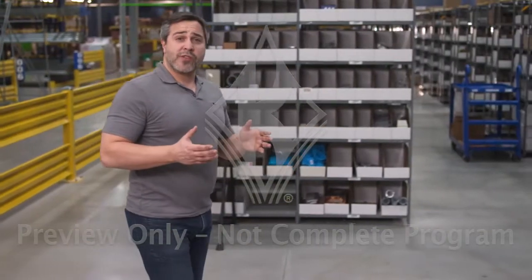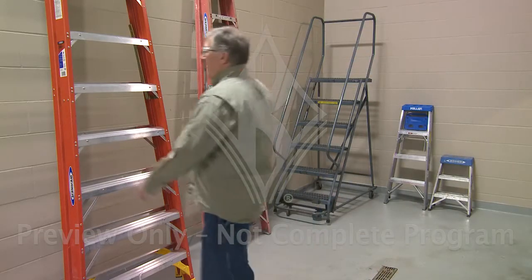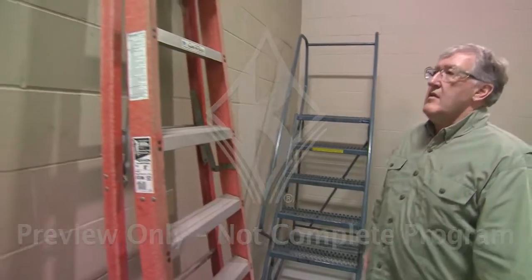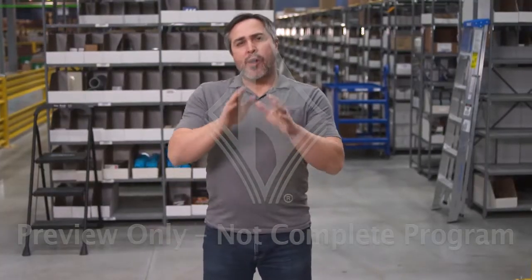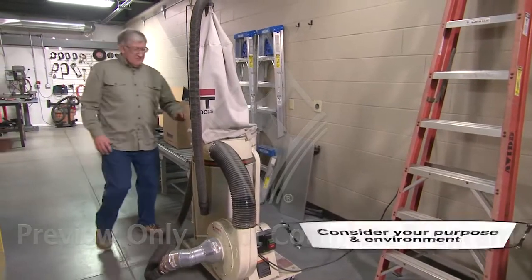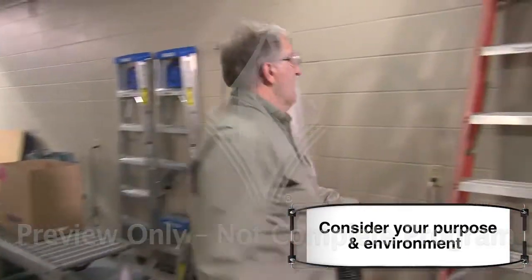While using a ladder seems pretty straightforward, you have many things to consider before taking that first step up. First, you'll need to select the right ladder. Will that be a portable ladder, a mobile ladder platform, or stand? You'll likely have at least a few options when it comes to choosing a ladder, but there are some things to consider to ensure you're selecting the right one for the job. Ask yourself, what are you using the ladder for, and what are the conditions in the environment where the ladder will be used? You'll need to be aware of any uneven surfaces or obstructions, and if you're working near sources of electricity, avoid ladders made of metal and choose fiberglass or wood instead.